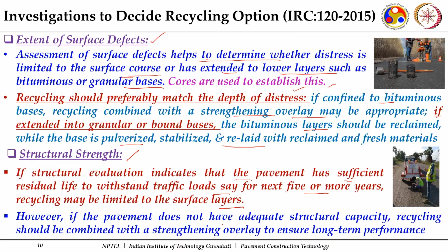However, if the pavement doesn't show adequate structural capacity, then the recycling should be combined with a strengthening overlay. So even the recycling of the surface course has to be followed by a properly designed overlay for strengthening, so as to ensure long term performance in that particular case.